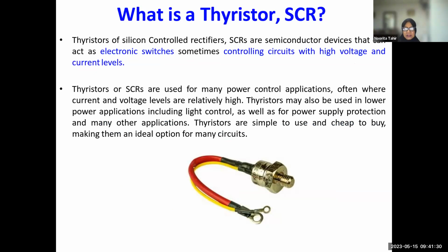Thyristors are constructed using the same technology as BJT, bipolar junction transistor, remember? And how then can a hysteretic device, a thyristor, be made from non-hysteretic devices, which are transistors? This is actually the utilization of positive feedback. Sometimes we also call it regenerative feedback.